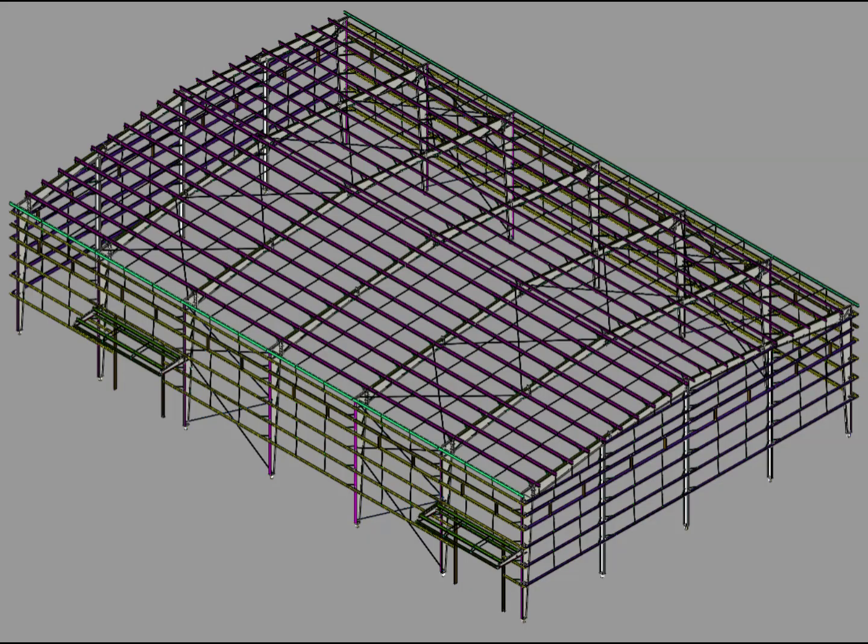When you are looking at a complicated roof framing plan for the first time, there may be many different lines representing different structural members. Some lines represent purlins. Some represent bracing. Some represent sag rods. And some lines may represent grid lines, dimensions, or other drawing information. Therefore, we should never identify a member only by looking at the line visually. We should always look at the member name, its location, and its relationship with the surrounding structural members.